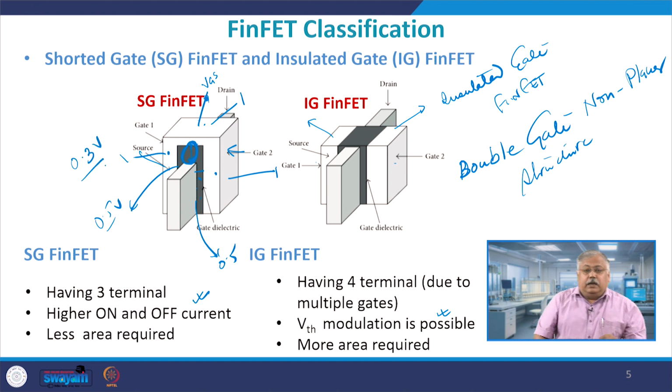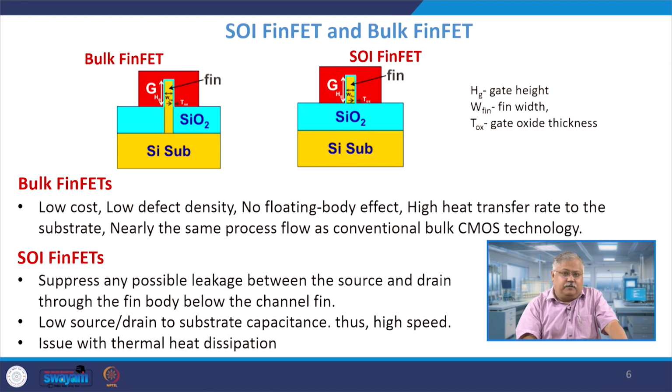So you see, by making the oxide growth asymmetric across the 3 edges of the design, I can have different values of voltages available to me at these 3 edges, correct, and therefore the threshold voltage will change. If you keep T oxide the same in all the 3 directions, then obviously you will never have this problem. This problem will be solved in the sense that exactly the same potential will be visible to all of them.